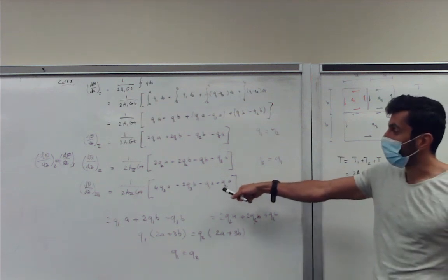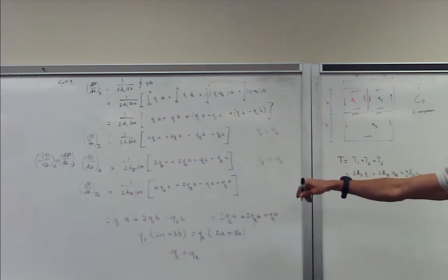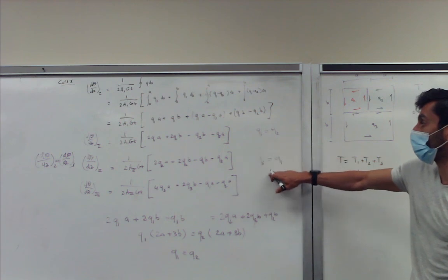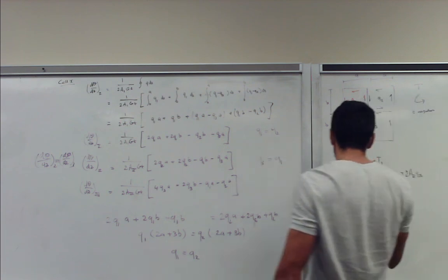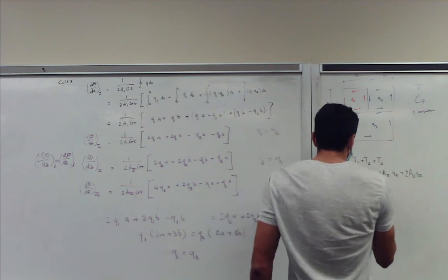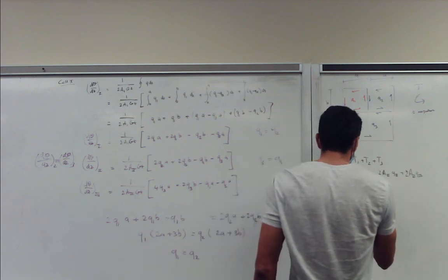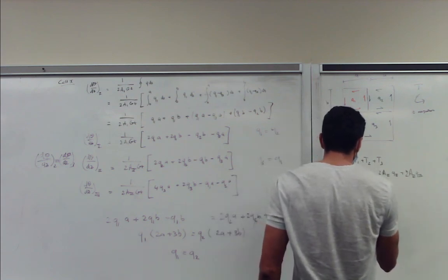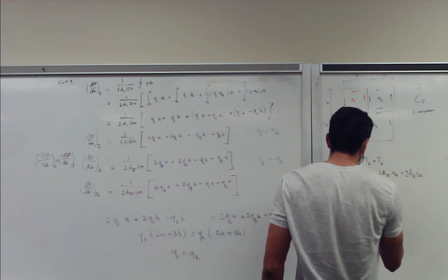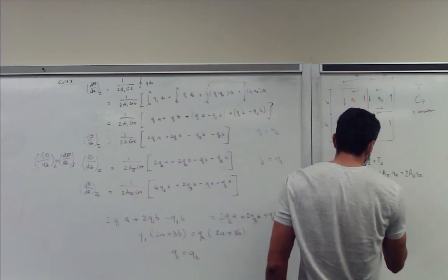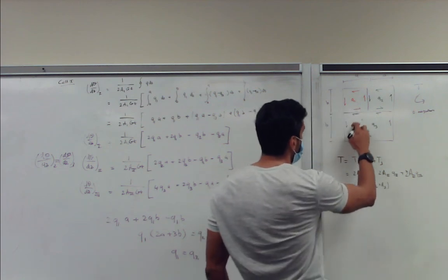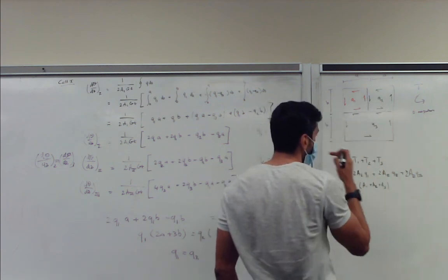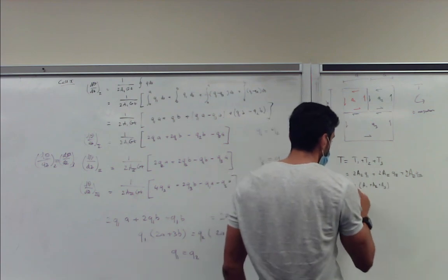But from the rate of twist equalities, we've got that Q1 is equal to Q2 and Q3 is equal to Q1. So basically what we can do is collect this. We get 2 times Q1, then the areas: area 1 plus area 2 plus area 3. This is 2AB, 1AB, 1AB, so that's 4AB times 2.